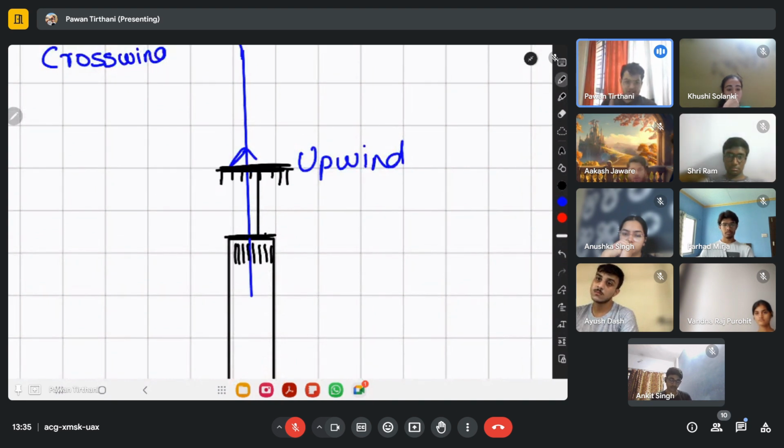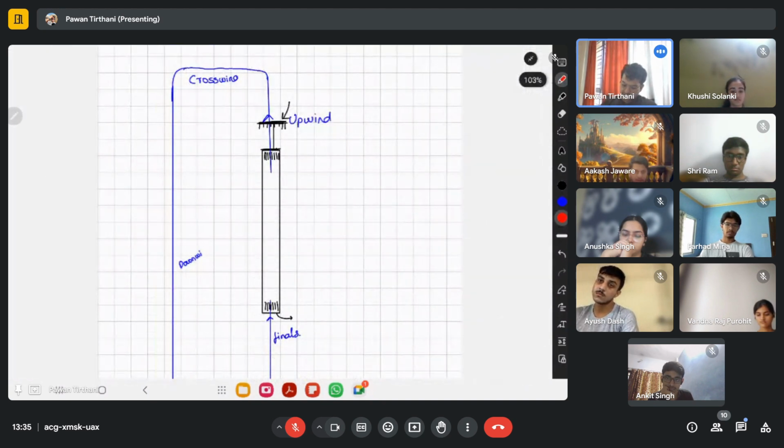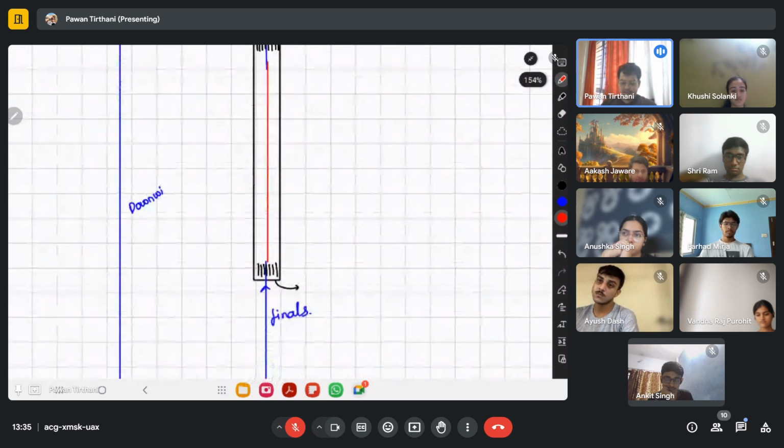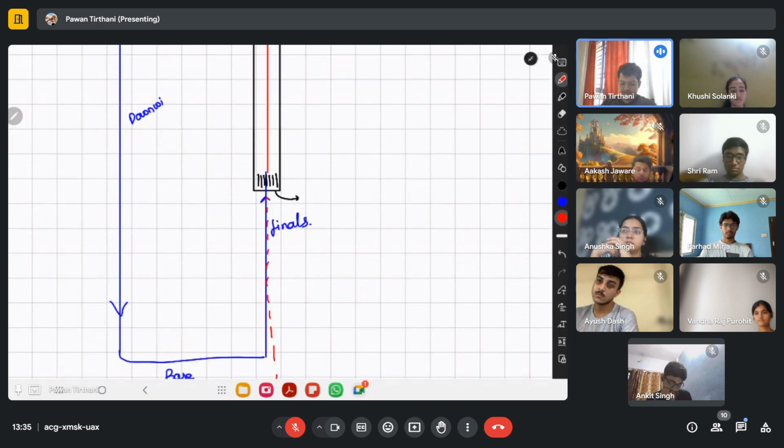तो लोकलाइजर का जो एंटीना होता है कहाँ प्लेस होता है? Where is the localizer antenna placed? It's placed here. It is located on the upwind end of the runway and it is centered on the center line. This is the runway center line, right? This is the center line. अगर मैं यहाँ से एक डॉटेड लाइन बना दूं वंदना, तो ये एक्सटेंडेड रनवे सेंटर लाइन होगी.